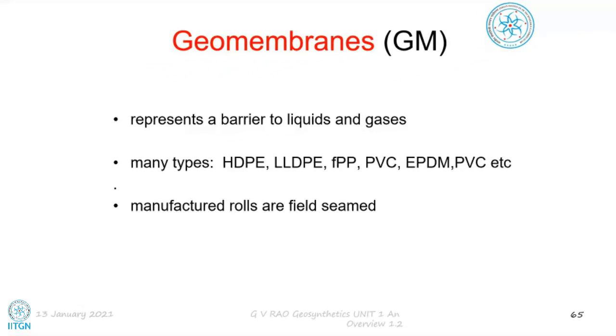And apart from all these materials like high density polyethylene, linear density polyethylene, and some kind of treated polypropylene, PVC, EPDM, we find that the thicknesses are going to vary anyway, but the most common are HDPE and PVC. And in these cases, PVC, of course, is preferred for water bonds and things like this. HDPE, as I said, is very highly resistant to both alkalis and acids. So we use it in landfills and other chemical applications. We can even store chemicals in HDPE lined ponds, basically.